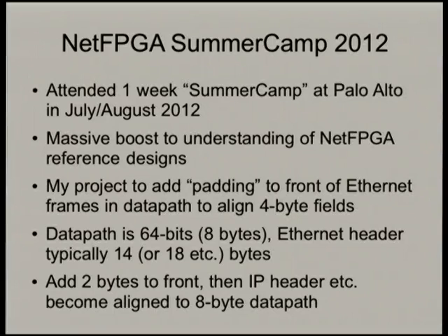So, okay, the question is, why are we even bothering putting USB on a gigabit switch implementation? Thanks for asking that question, Martin, I did miss some key information. These ARM system on chips are designed for mobile devices, and mobile devices rarely require a wide network interface, so they don't have them. They do have USB 2. So if you want to get data in and out of these low-cost, low-power ARM devices, you have a number of options, but USB 2 is probably the fastest option. Some of them have built-in Wi-Fi, but building a cluster out of Wi-Fi devices...